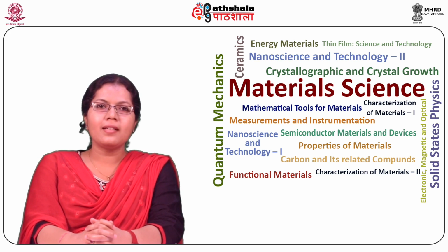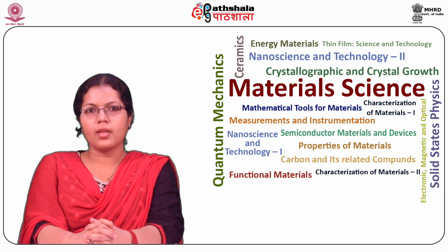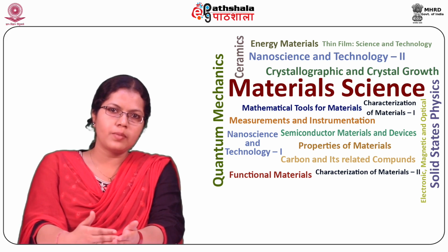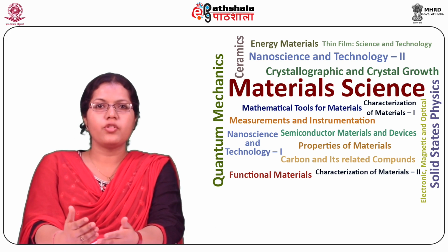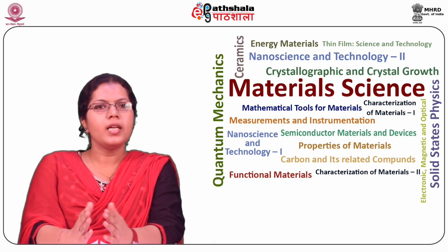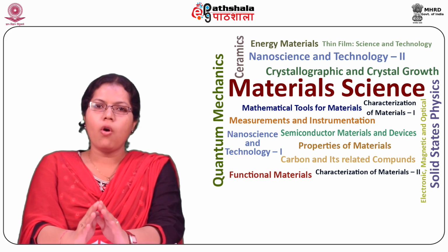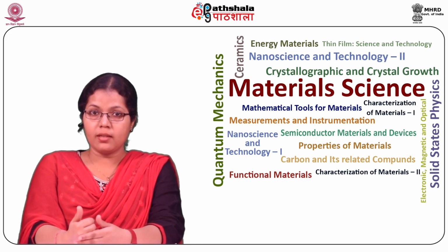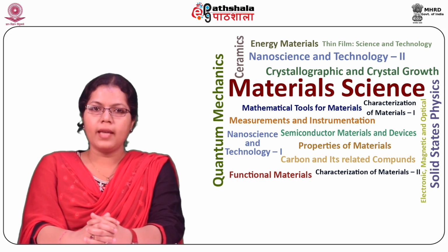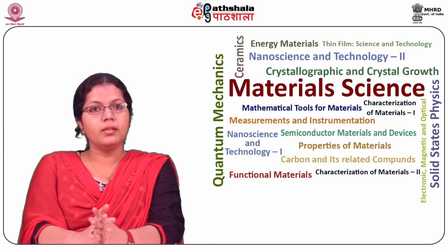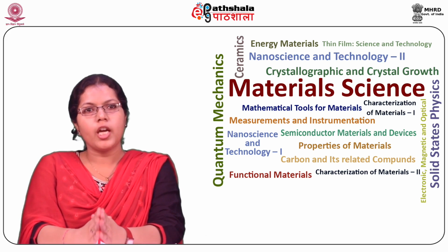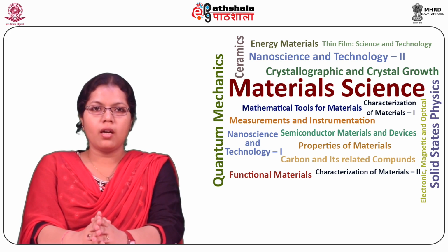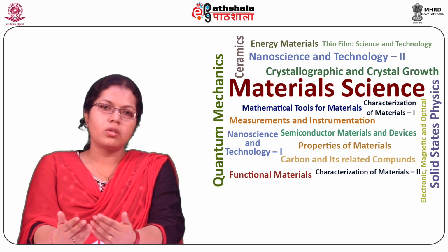So students, now let us learn about the smart sensors. Transducers or ordinary sensors help us in sensing or controlling the process parameters such as temperature, pressure, strain, flow, pH, etc. Smart sensors provide functions beyond all of this. First, a smart sensor acquires the data from the instruments. Second, the conditioning of the signals is also done by the smart sensors. Third, the smart sensors can convert the measurement into the attribute units, and also transmit the data to a network by wireless method or through a wired line.